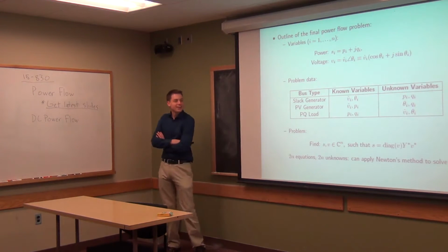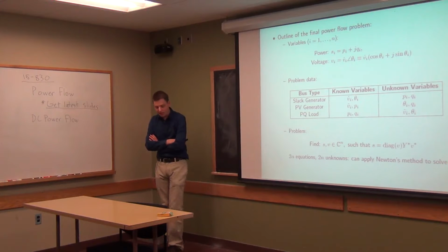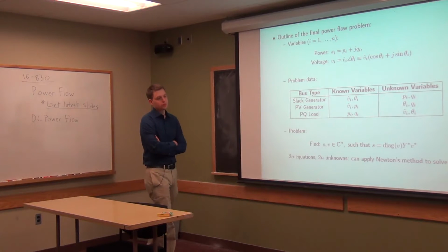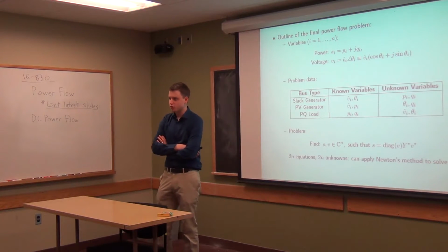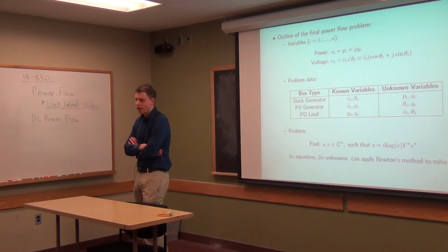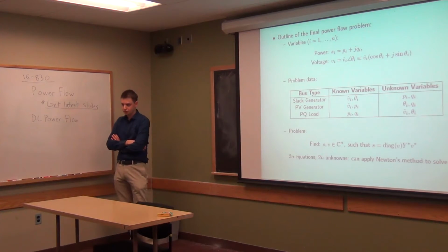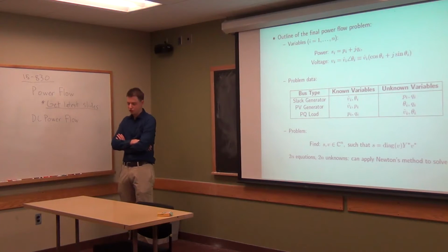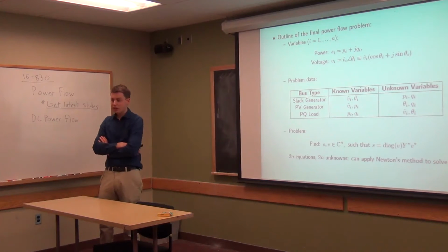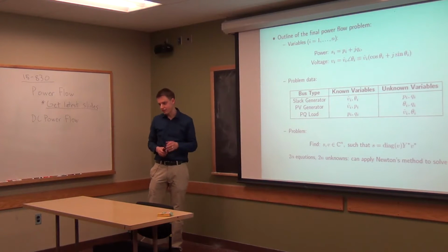All right, so today we're going to keep talking about power flow. To highlight what we did last time, remember, the basic idea was we want to know, from a bunch of generators and a bunch of loads, how current and how power will flow in the network. The tricky part was that we can't easily know all the voltages and currents, at least not the absolute voltages and not the complex voltages and complex currents. And so it's hard to solve this system like a linear equation, as we typically did in linear circuit analysis.